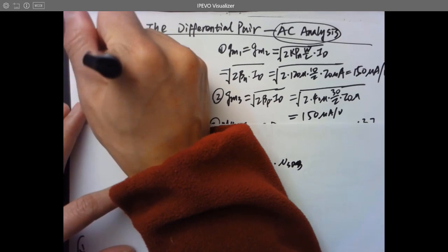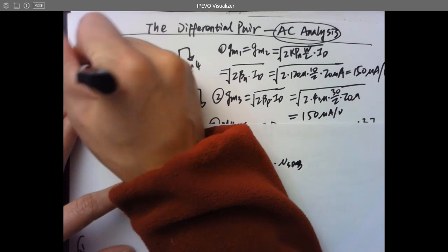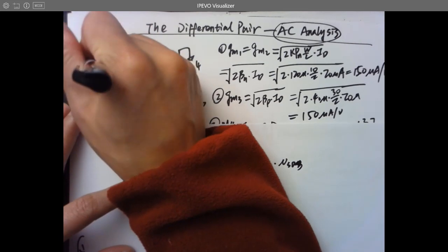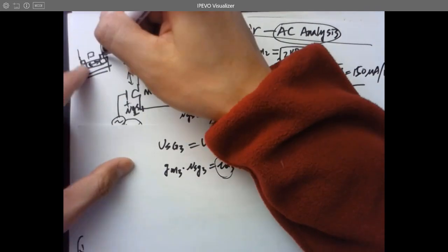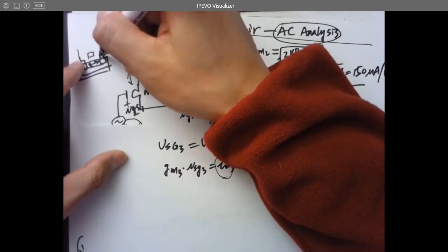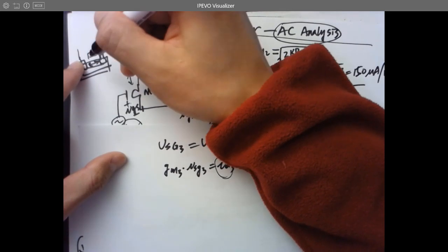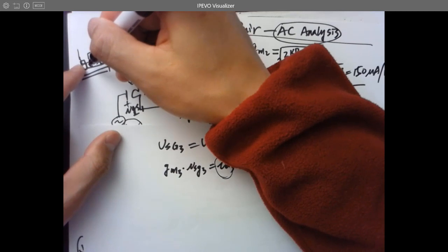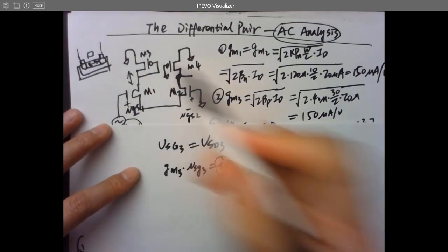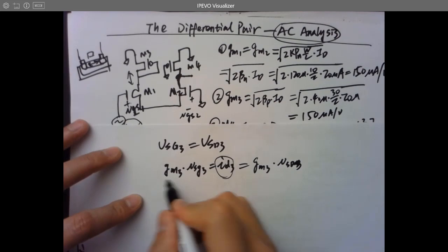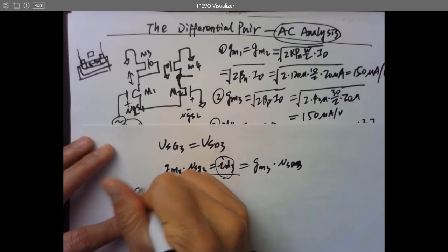Whether NMOS or PMOS, it has a channel, and that's the N well. The voltage drop across these two terminals divided by the current, which is ID, equals the equivalent resistance of the channel. So when you have a gate-drain connection, you can use this equation to find out the channel resistance of the PMOS.